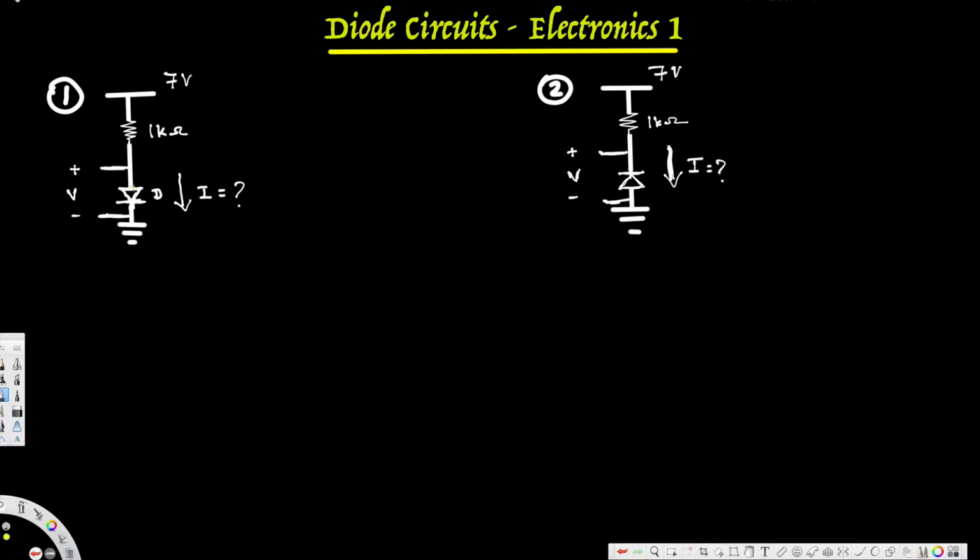If the diode is on, this is going to be a short circuit, and also we have to know that current always flows from anode to cathode. So this point is anode, and this is cathode. For this one, this is anode, this is cathode. So we have to assume this direction because it goes from anode to cathode. Okay, so we write our new circuit like this.